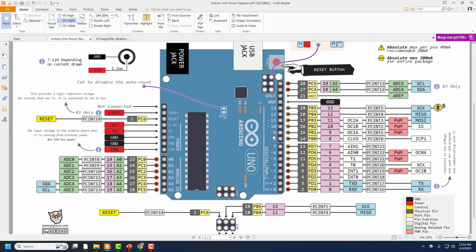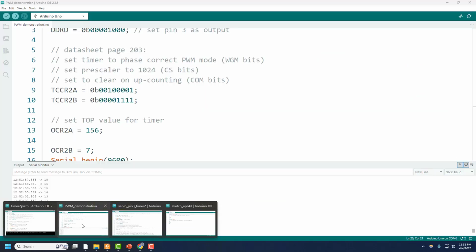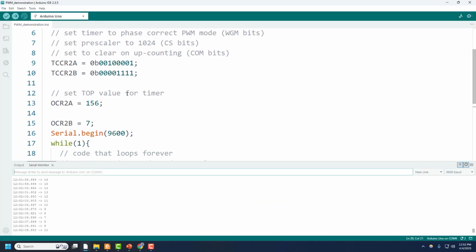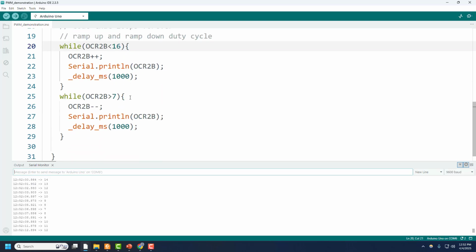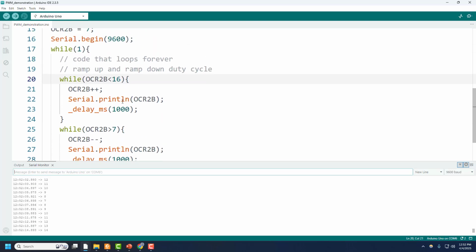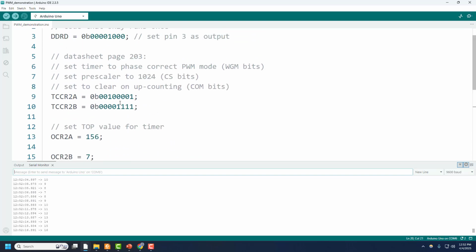Think of it like a group of people that only have 3 stopwatches to go around. If one person is hogging the stopwatch, or somebody else tries to grab the stopwatch while you are in the middle of using it, you can run into weird conflicts in your code, depending on which parts of your code or which libraries assume they have access to a timer. So if you do it all manually yourself like this, even though it's painful, then at least you know exactly what is going on in your code.